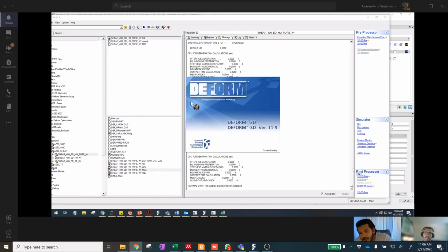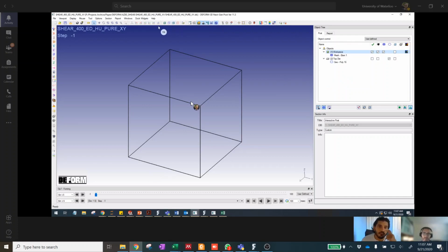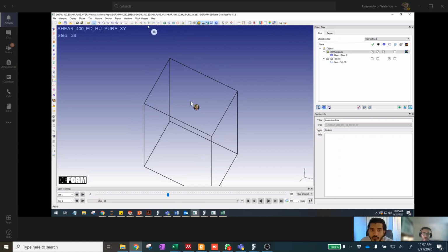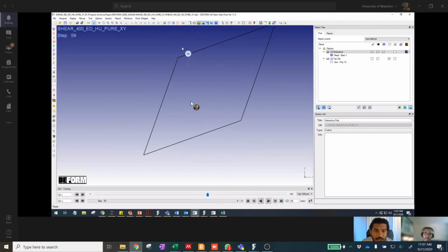The other thing you can do to simplify this type of work is deactivate the strain rate effects and only look at one material curve. Right now you're imposing a velocity, but the velocity gradient throughout the element is changing. That's why when you're looking at the material curve, it's slightly interpolating at the end between slow and faster. It's not always 0.1. It starts as 0.1, but it's not always 0.1. If you remove strain rate effects, it's always referencing that one material curve. And to be honest, for what you're trying to do, the strain rate effects are irrelevant. That's a good point. Okay, everything looks better. See the stresses that you're getting?